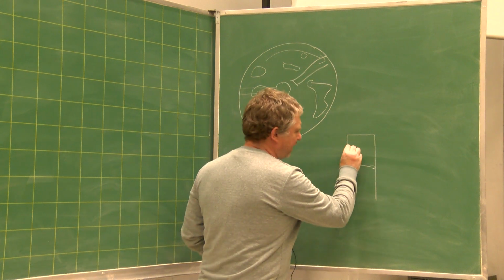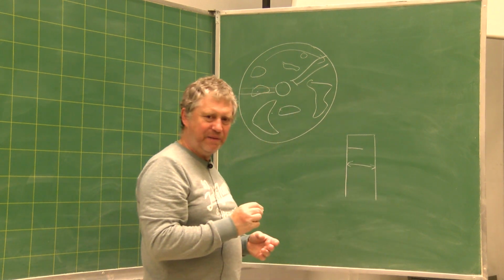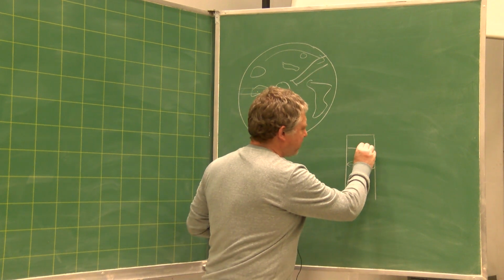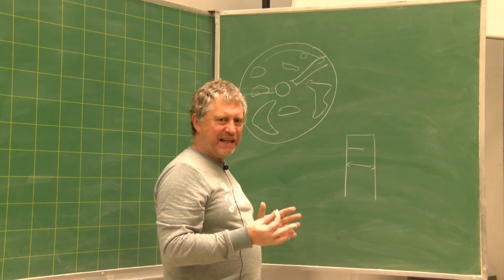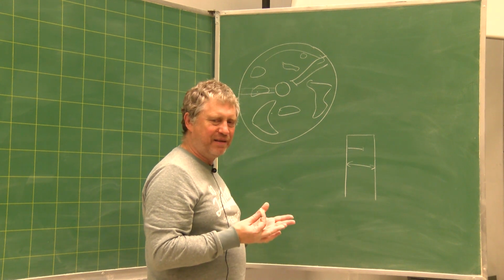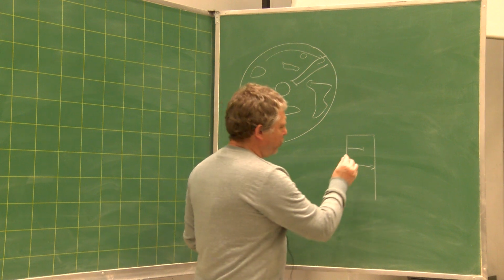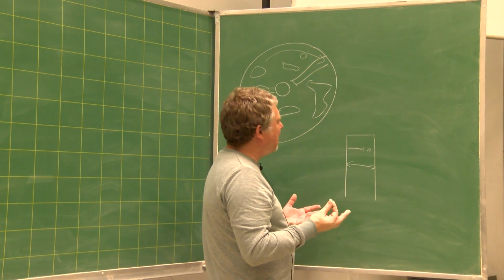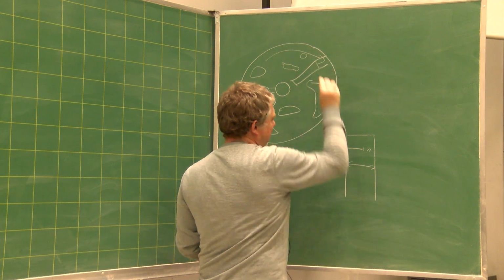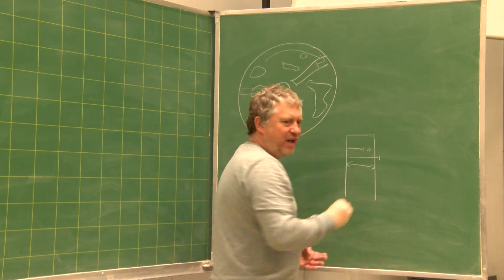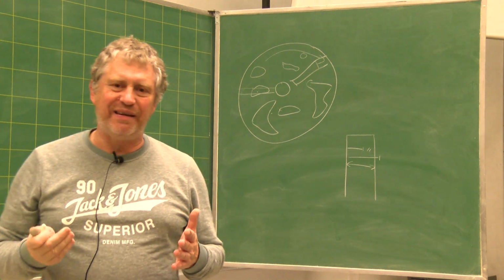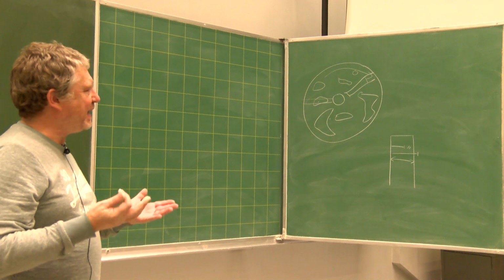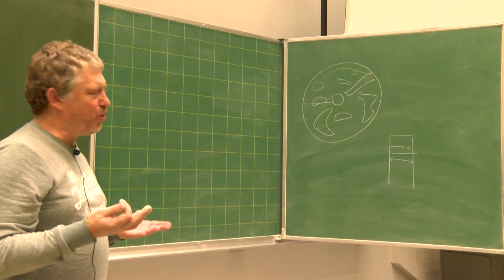If at this point the perturbation is only there, the blade will not react wrongly, because you still have this part of the blade that is sane. But if, when you arrive here, the perturbation is here, you have contaminated the whole blade, and then the whole blade will react non-adequately, and that can certainly lead to a surge.